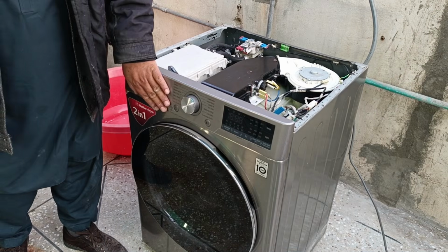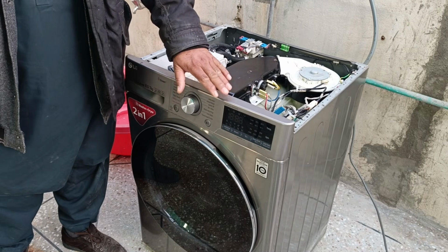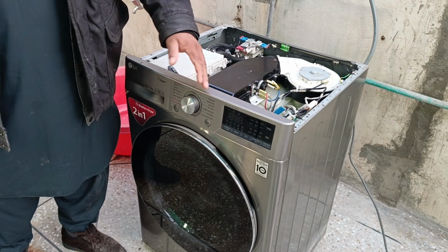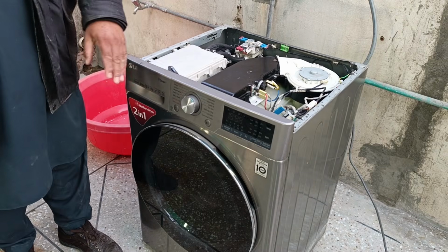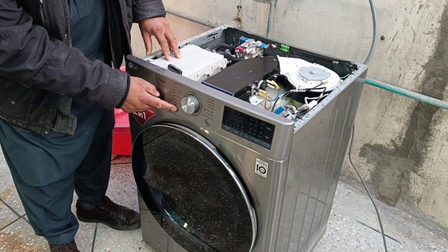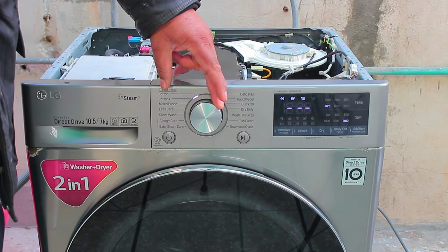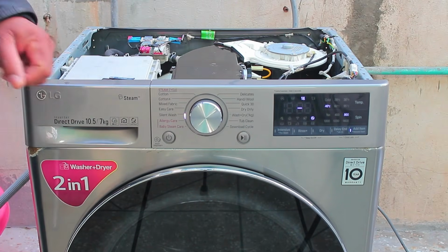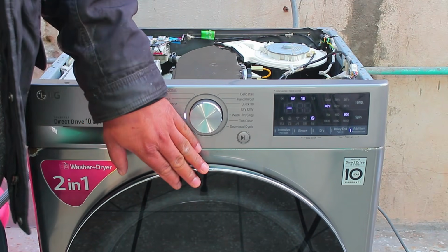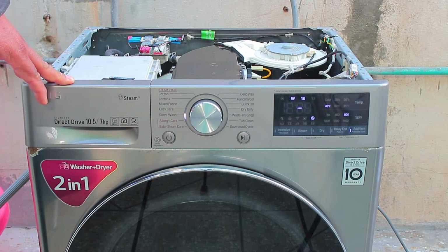Now what we will do is try to restart the machine to clear the error, because I forgot to close the door properly. That's why resetting the PCB is very important. If it still does not reset, then you can disconnect the power supply for a short time. When we turn the machine on, the error does not appear. This means the machine has been successfully reset. I also heard the sound of the door locking, which confirms that it is working properly. So now the machine is completely okay.